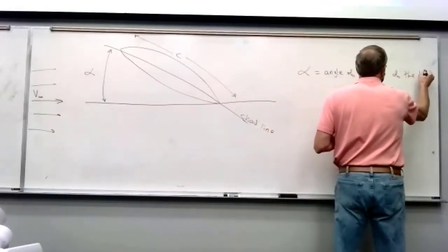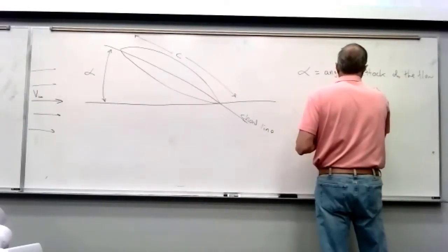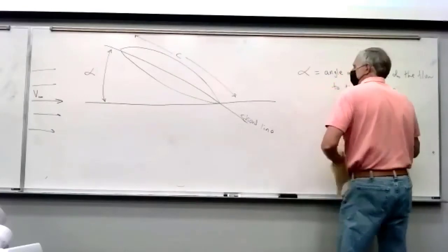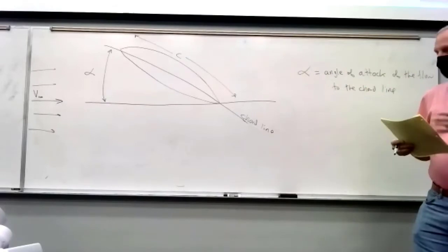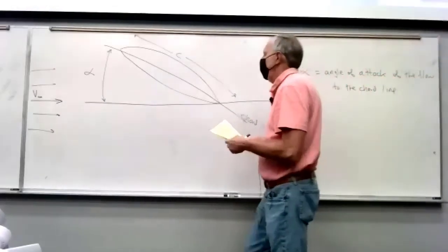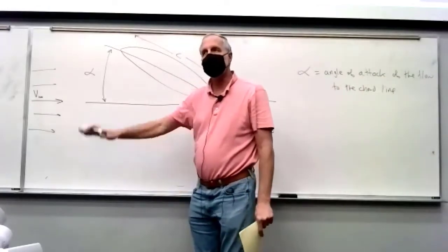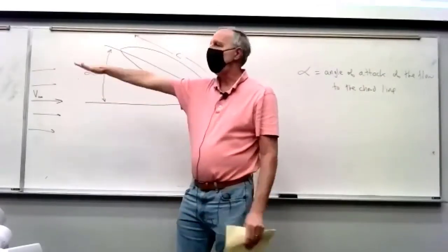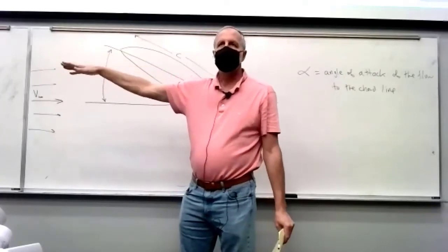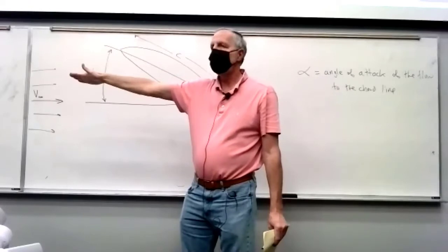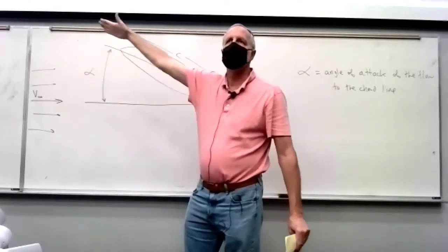It's the angle of the flow to the chord line. And as you might imagine, the steeper that angle, the more force we're going to get from the air pushing up on the airfoil, just because it's tilted, right? Hold your hand out the window of your car when you're driving down the road, not too fast because it will hit you and it'll hurt. You tilt it up, you're going to feel the force of the pressure on the bottom of your hand pushing your hand up. Right?